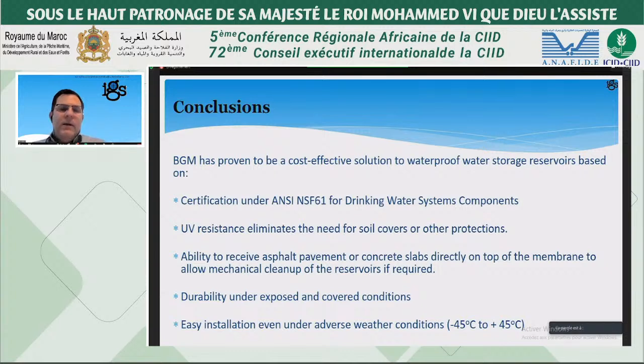It has also the ability to receive asphalt pavement or even a concrete slab directly on top of the membrane. So it allows, in this case, mechanical cleanup the reservoir when required. And it's also easy installation, even under adverse weather condition, like high temperature or very low temperature.